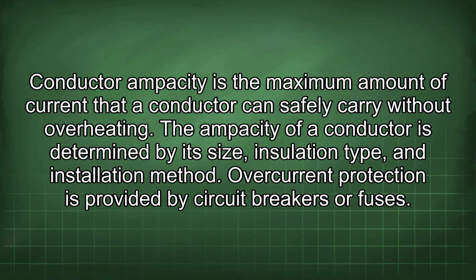Conductor ampacity is the maximum amount of current that a conductor can safely carry without overheating. The ampacity of a conductor is determined by its size, insulation type, and installation method.